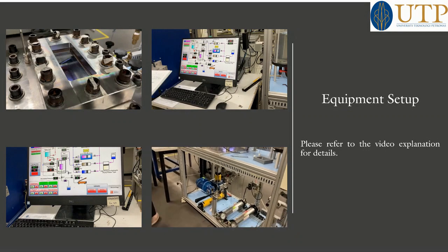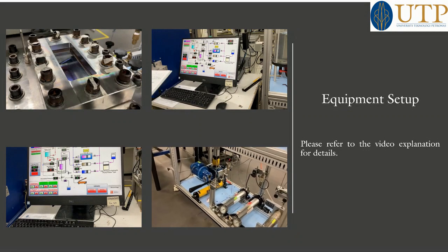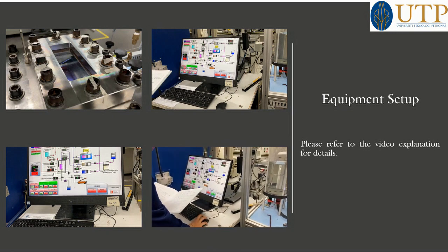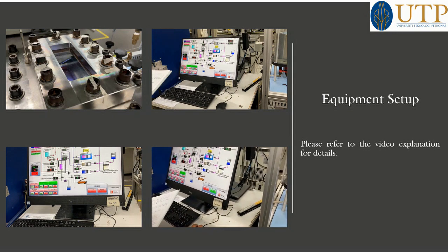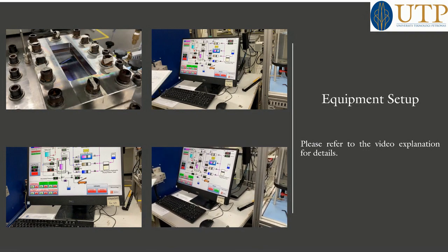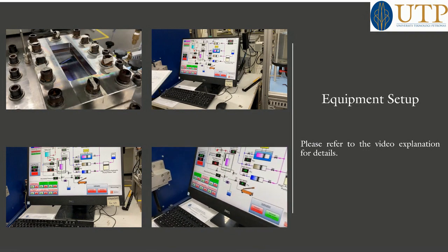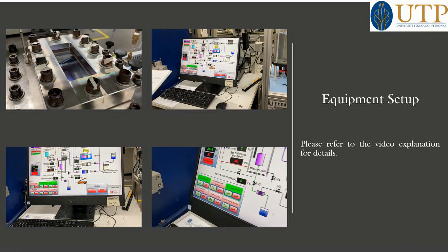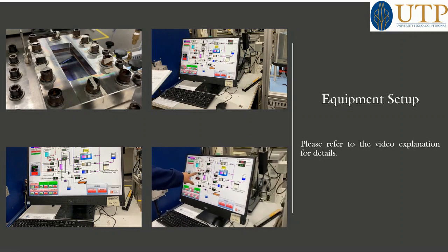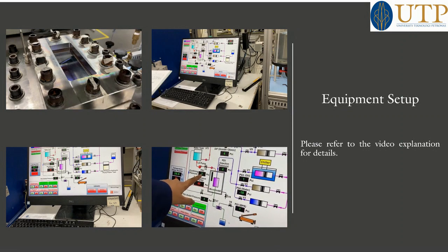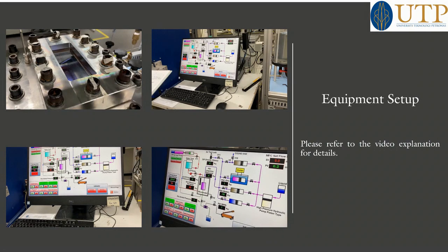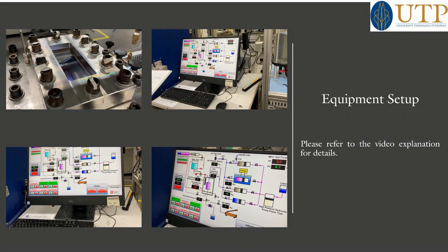And now they say switch on system button. So I'm switching on system button. Okay, now system button is on, and we will see that our confining pressure will increase very soon. So when it is 40 to 45, then we can start our further procedure.